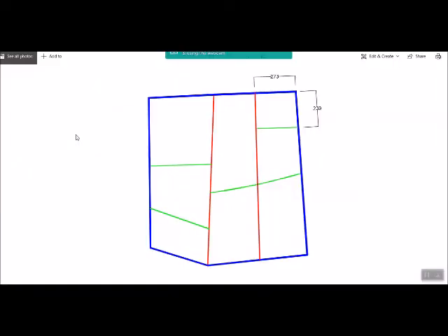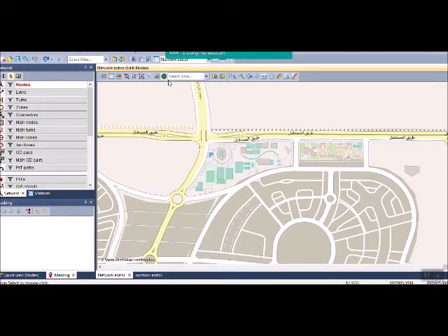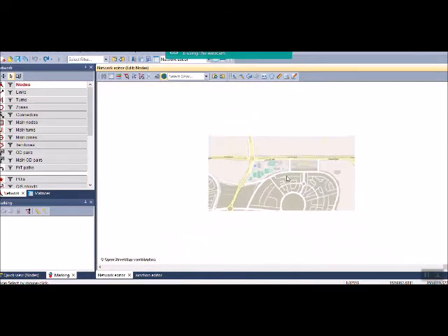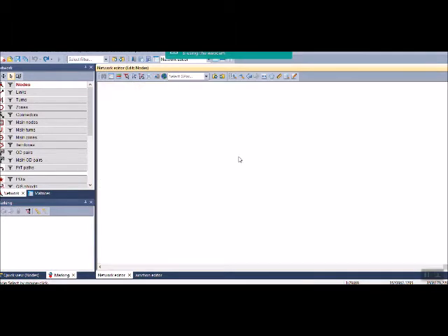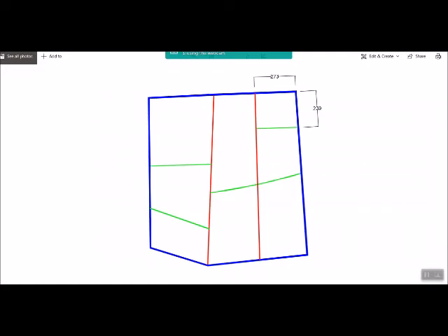In this part of the video, we're going to build our town model and then calculate the Skim matrix. First of all, we have our hypothetical network here, so we do not need to open the map, and we're going to close it. Second, we are going to insert our image, which is a PNG or JPG file. This image should be scaled, and we have two dimensions here: 273 meters and 239 meters.